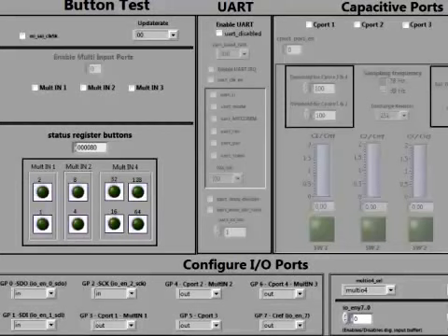Now we call each of these pins a multi-input port. On each multi-input port you can connect up to a maximum of 8 keys. Thus for 3 multi-input ports you can connect up to 24 keys. On the PS09 evaluation board, however, there are only 8 keys connected across 3 multi-input ports: 2 keys on multi-input 1, 2 on multi-input 2 and 4 keys on multi-input 3.